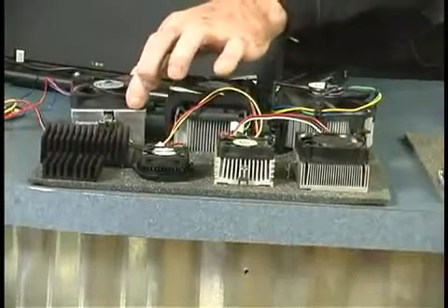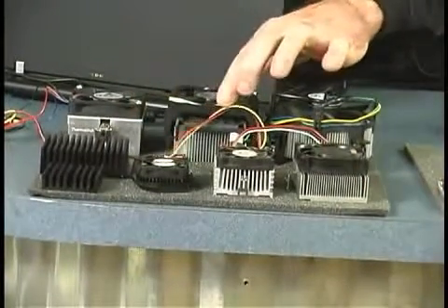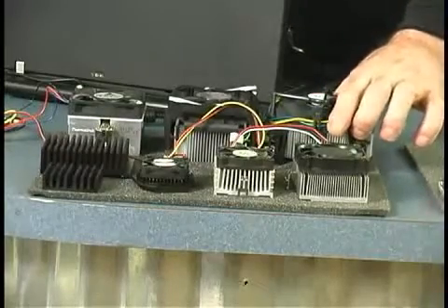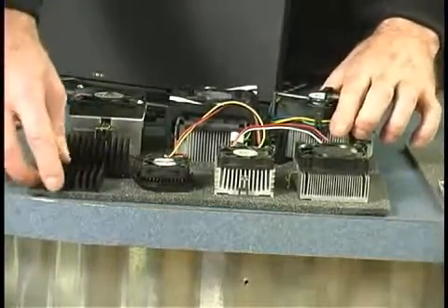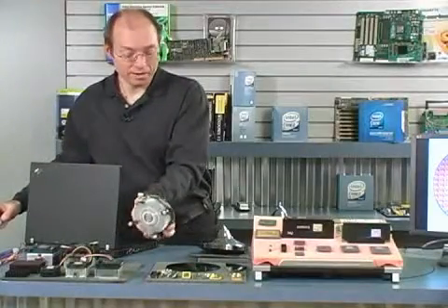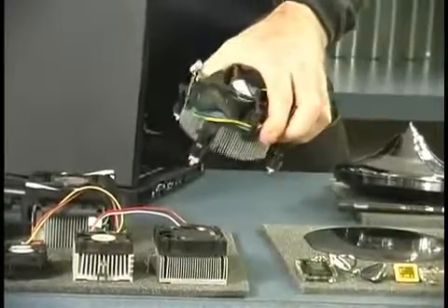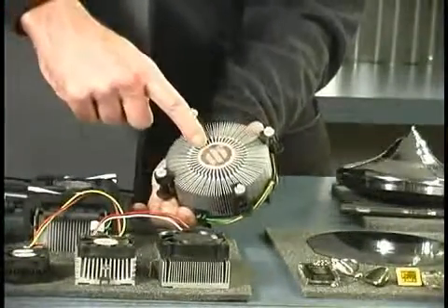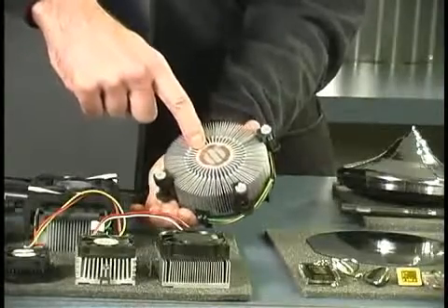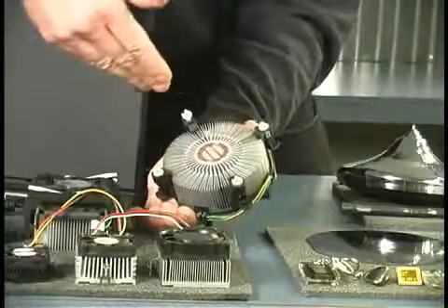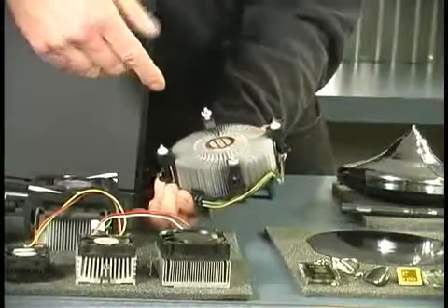Over here, we're up to 1 gigahertz, 2 gigahertz, and then 3 gigahertz and beyond. As you can see now, what started out as just a small passive little heat cooling device is now a massive finned assembly with a large fan. Sometimes in many of the newer heat sinks, they also use a copper core. Copper is one of the best conductors of heat, much better than aluminum and many other metals.